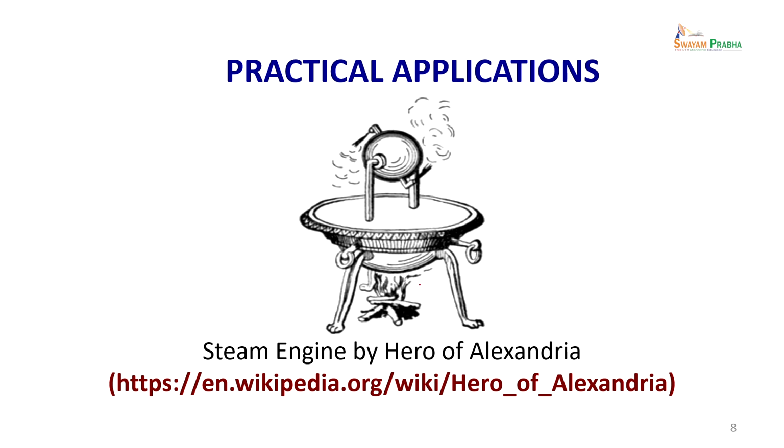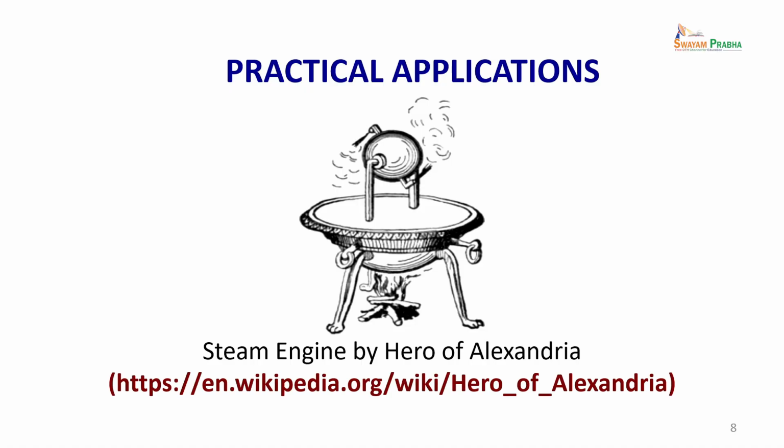The heat liberated is used to convert the water in this spherical container into steam, and there are two nozzles. The function of the nozzle is to enhance the velocity, because the steam which is generated in the boiler or whatever steam generating device has high pressure and temperature, but the velocity may not be that significant. So, generally the nozzles are used to enhance the velocity. This was one practical application invented by Hero of Alexandria, Egypt. This was considered one of the steam engines of that period.